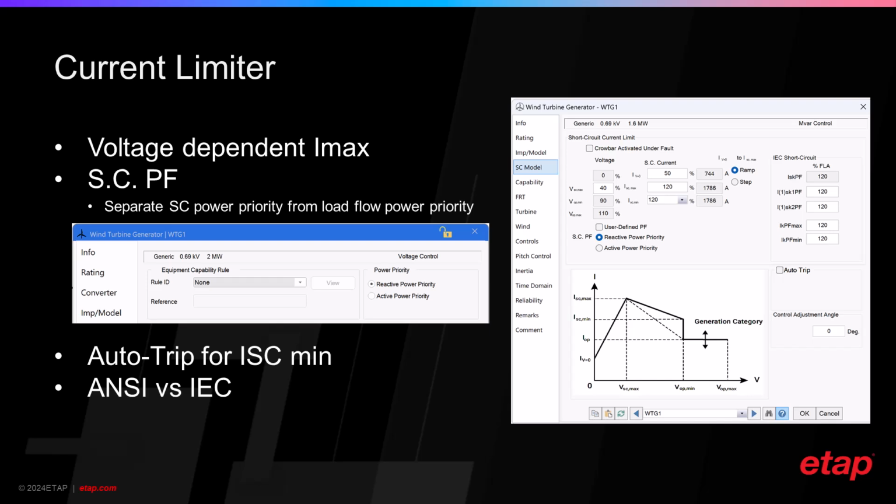What we do in short circuit is that we are going to have a certain number of iterations. As we are going through the iterations, after a certain number of iterations, in ETAP our default is around 6. So if by 6 iterations we go outside of the deadband, we inject. If we come back to the deadband region, we stop injecting the ride-through current. Now, after the 6 iterations, if the voltage goes outside the deadband, we're going to lock the voltage ride-through or fault ride-through mode. This means that this curve is going to stay continuous, and we're going to continue injecting reactive current per this curve.